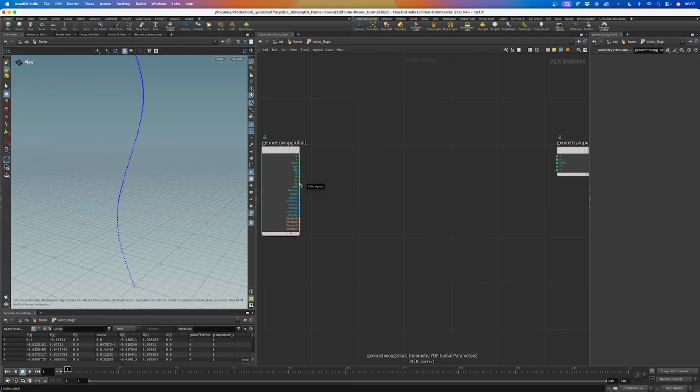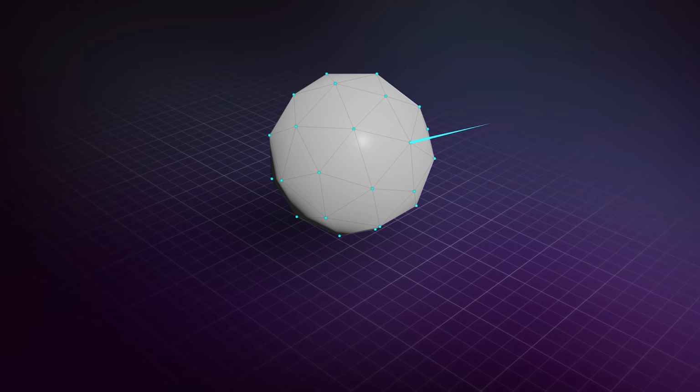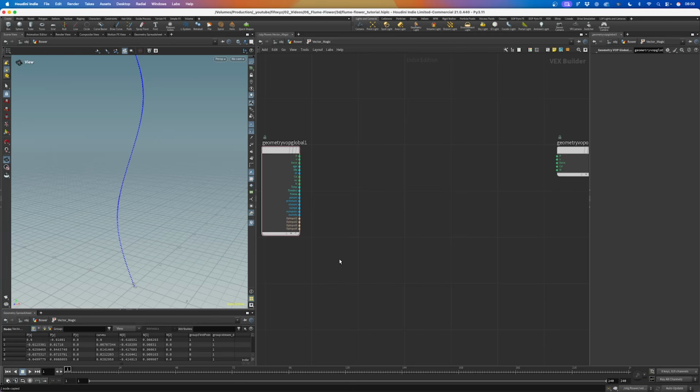What I want to do with that is I want to use a cross product in order for the normals to not follow the shape of the curve but stick perpendicular to this kind of curve shape. So let's maybe have a little recap what a cross product is. Back in your math class, I guess you should have learned that whenever you want to multiply two vectors, let's call them A and B, you get a new vector that is basically perpendicular to both A and B. And that's what we're going to use now.